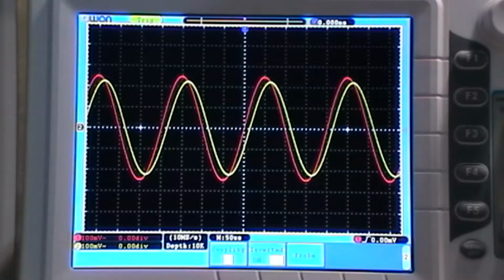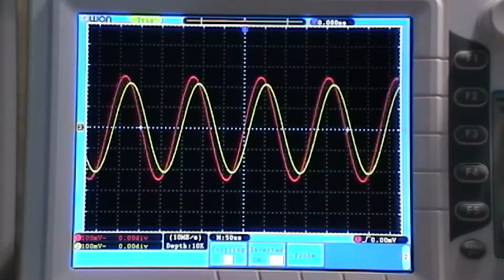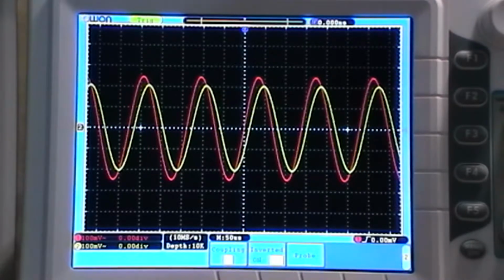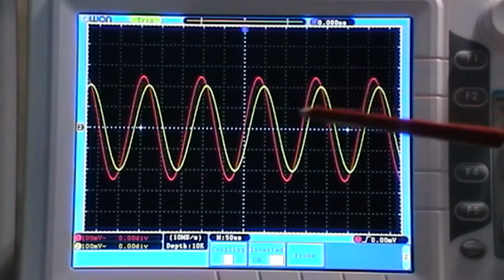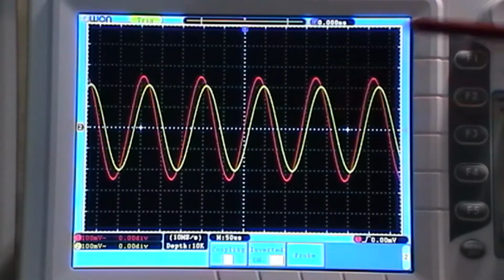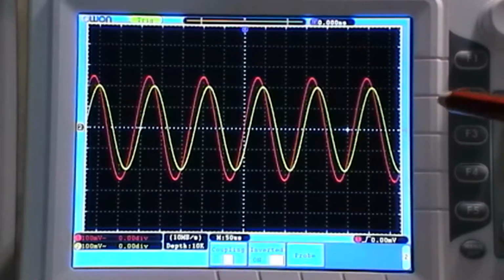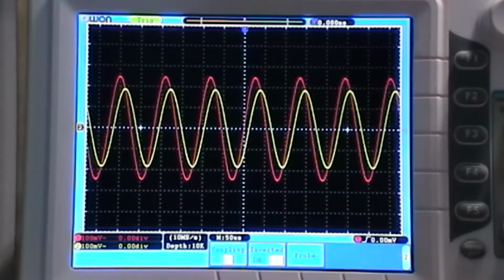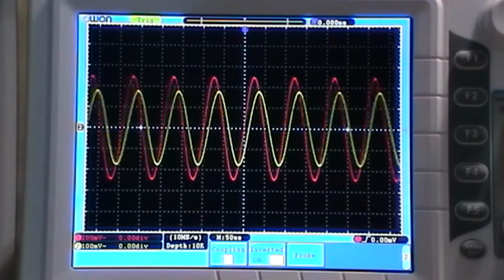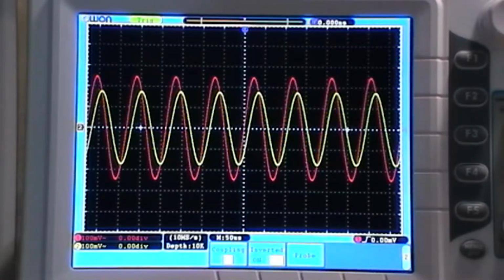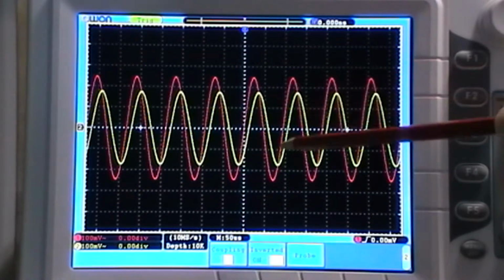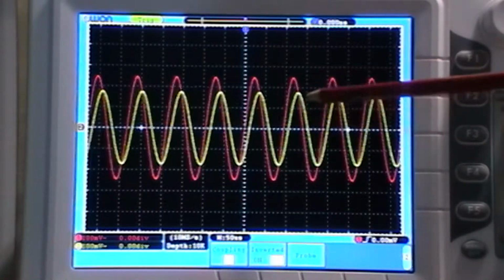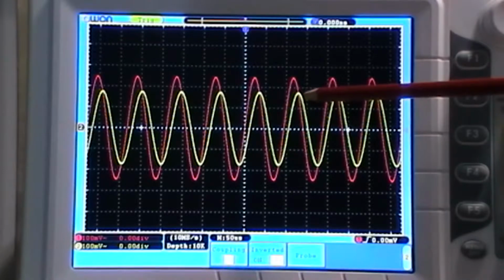And let's crank this right up then to the 10. As you see, it is attenuating as I crank this frequency up, but not by a great deal. It's only slightly attenuating that signal, and I want it up at 10.6, so 10.6, there we go. Again, have I got my -3 dB from the original signal? It looks about right, same phase shift.